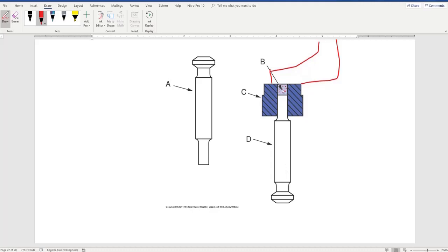So how do I control the weight here? I can control it by the lower punch. Then the lower punch will be responsible for controlling the quantity. But the problem is, what is the problem? If I want a tablet with, let's say, 500 milligram weight, how can I know that this space is 500 milligram? I cannot know. This is a problem, because what you have here is a volume. So you want a volume that corresponds to the weight you require. You require 500 milligram. So what do I do?